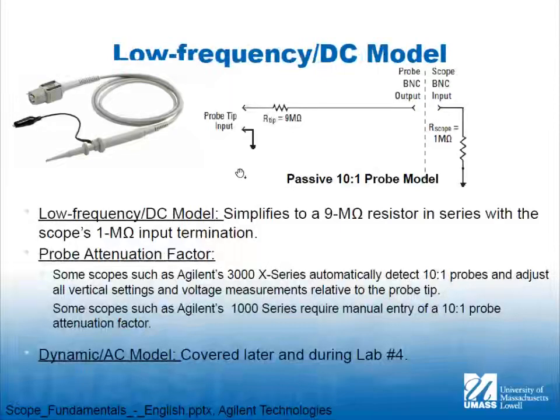So we can get a cheap probe, which doesn't have that compensation, and it is literally just cheaper. And again, the more we have, the more economical we have to be. Not that money necessarily has to be an object, but when we start to get into very large numbers, the density causes us to have some simplicity. So if you're wondering where this is going, I'm going towards a logic analyzer, something that has lots and lots of connections. So I'm stepping through to that point.